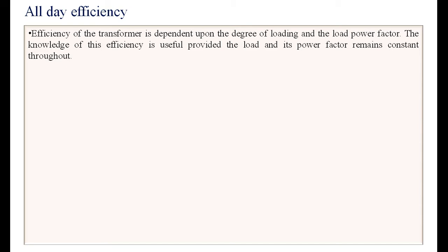For that purpose, we devise an all-day efficiency. Instead of calculating the efficiency in terms of output power in watts, it is calculated in terms of output in kilowatt hours, and the input is also in kilowatt hours, because the load is varying on the distribution transformer.